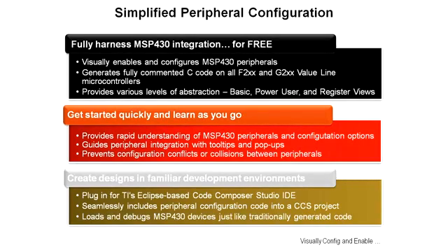That way you can come up to speed and get a rapid understanding of the MSP430 peripherals and what configuration options are available to you. It will guide you through the peripheral integration with tooltips and pop-ups, and it prevents configuration conflicts, like trying to use the same pins for two different things or collisions between the peripherals.